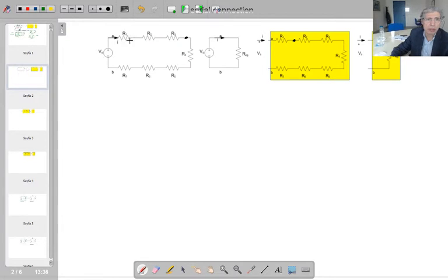Why are they connected in serial? Consider R1 and R2. One of the terminals of each resistor is connected to a node. This is that node, and there is no other resistor or any other element connected to that node. Therefore, R1 and R2 are in serial. When they are in serial, the currents of these elements are equal. Let's prove it.